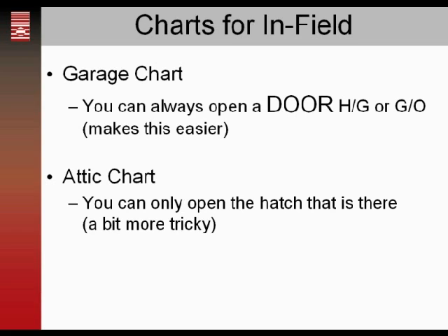Attics, opening an attic hatch can be more tricky. You want to make sure you're not going to be pulling insulation from the attic into the house with the blower door running. You can pressurize the house to do that test if you're concerned about that. And these numbers work either depressurization or pressurization.